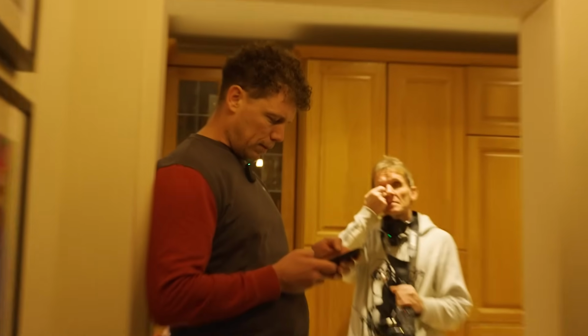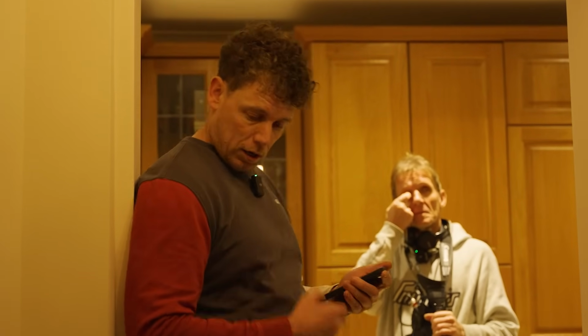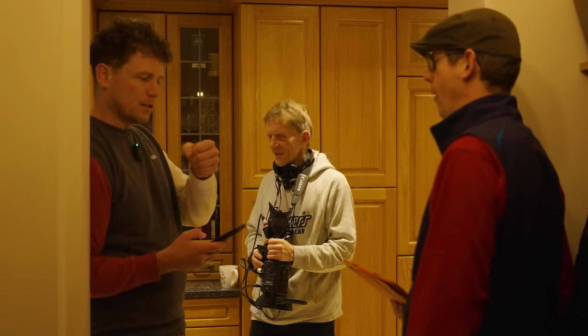I did wonder about having a new water main coming into the house to go into a water softener. Well, the water main looks fine because it's 25mm, I think. Let me see, I've got a torch in there. Is it 20mm? It's plastic, so it's been upgraded. 20mm is the same as 15 basically. The main thing is that it's not lead, because lead squashes over time.